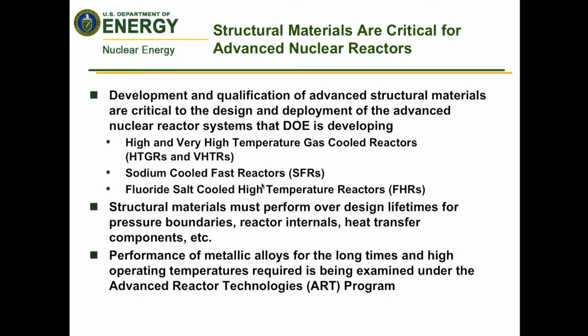Why do we care about advanced structural materials and how do they fit in the overall program? It's critical to qualify and develop advanced structural materials for these advanced nuclear reactor systems that we're talking about deploying within DOE: the high temperature and very high temperature gas-cooled reactor systems, sodium fast reactors, salt-cooled reactors. Structural materials have to be able to perform over the full design lifetimes for things such as pressure boundaries, reactor internals, heat transfer components and such.